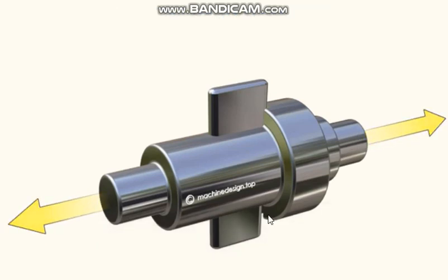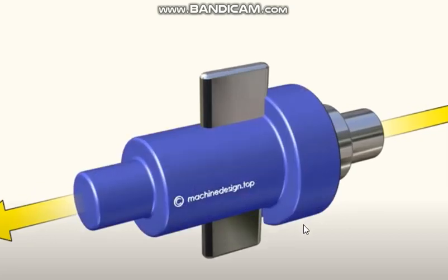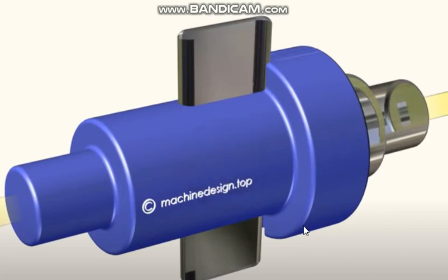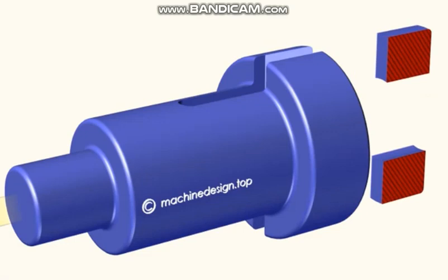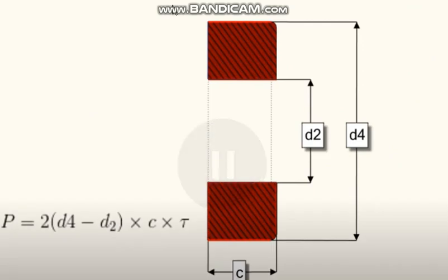Again, now this is tension, this is the socket. What they are showing is, suppose in this socket, because of the tensile pull this side, because the cutter is in the middle, this portion here and down here may fail in shear. Now they will show. Yesterday I was talking about some cake pieces falling. This is like that, those are the areas which should fail. Top also, bottom also, and the back side also. So you should be able to compute the area now.